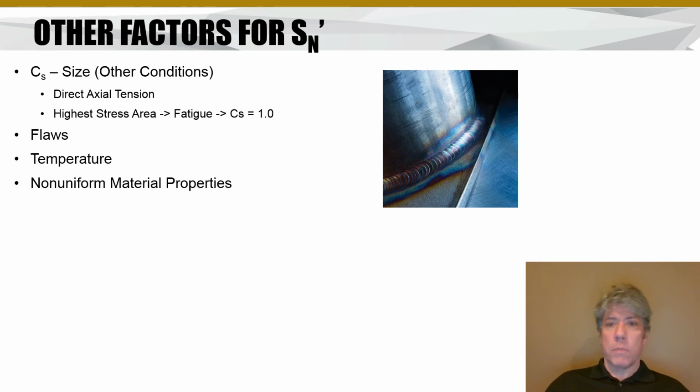Now, of course, some materials are processed in a certain direction. Think of rolling out hot rolled steel or cold rolling material. And what that ends up doing is making the properties different in different directions. So you might take a part that's been drawn or rolled in one direction, make a shaft out of it, rotate it, test it, and you're testing the strength in the direction of the processing, right? So it might have higher strength.